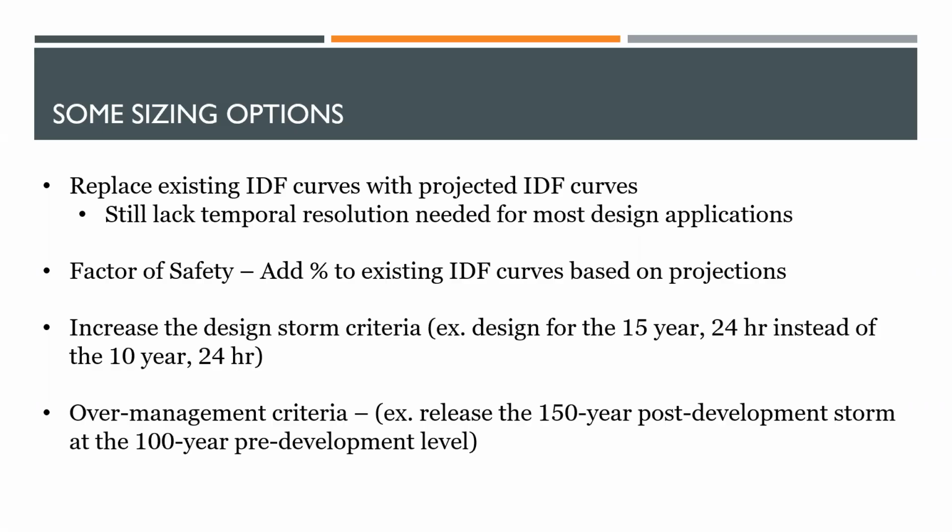So as I mentioned, you can take these projected IDF curves for future years and use them as IDF curves. There are options for extending them down or scaling them to those lower temporal resolutions. But we do lack a lot of that resolution for a number of design applications. And I understand that there are going to be some hesitancies, as you understand the uncertainties around some of those curves, to not just copy and paste them and use them in your manuals. So there are other approaches.